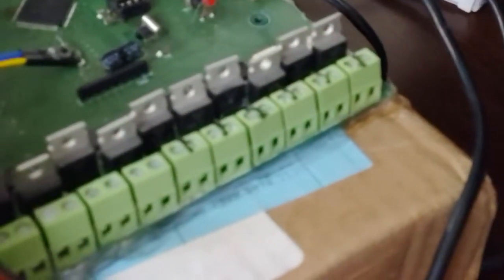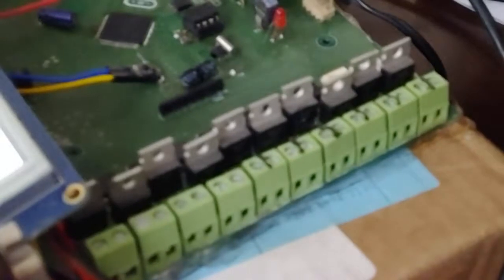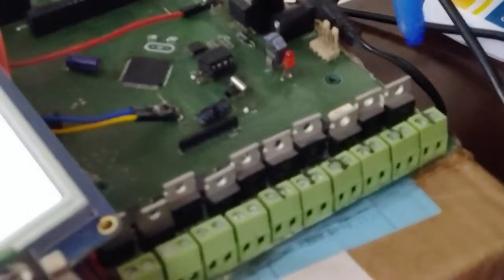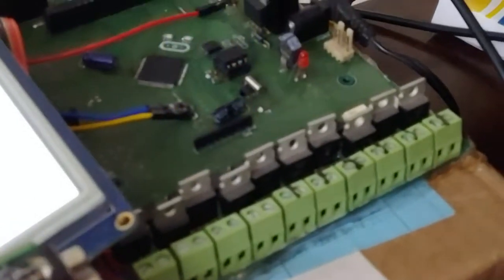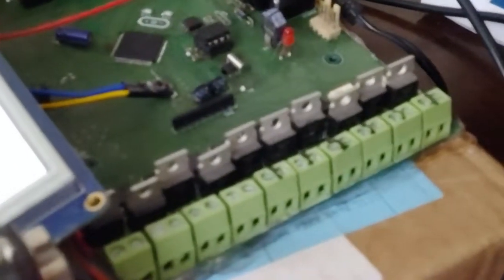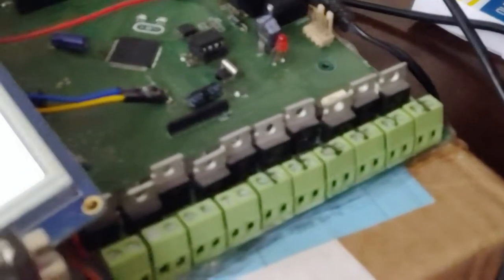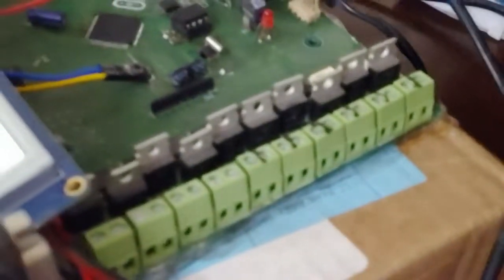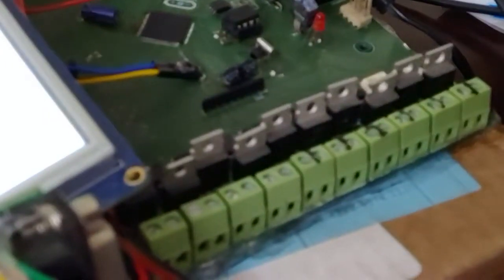And the other fixed loads, that is, from the leftmost position, from here right down up till here, there are a total of 8 thyristors which are controlling the fixed loads. So fixed load on-off control is fully static and it is not based on any kind of electromagnetic relay, thereby reducing the noise and other problems which can be generated.